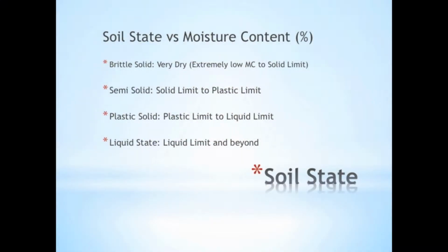The Atterberg Limits test references ASTM D4318. This test helps in discerning between silt and clay. It describes a soil state with moisture content, primarily. If the moisture content of a soil is very low compared to optimum, it is considered a brittle solid.